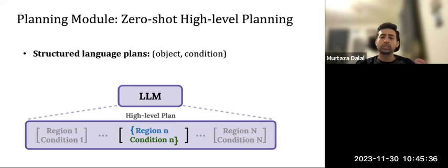And we also introduce stage termination conditions. Basically, these are exit conditions for some sort of skill. So for example, grasped, placed, and opened. Those are some examples that we use. Crucially, we only need to define a verification step, estimating that this sort of skill is terminated, not predefining the local low-level behavior that you need in order to do that skill. That is what's difficult.